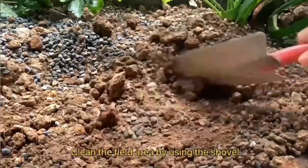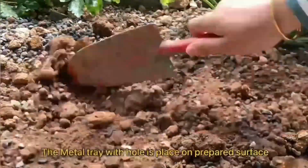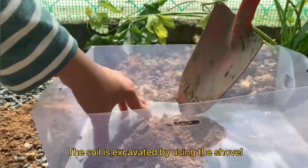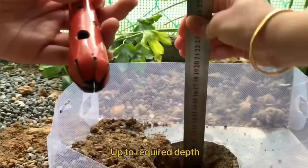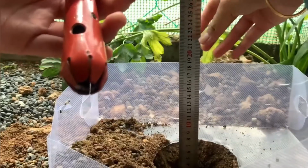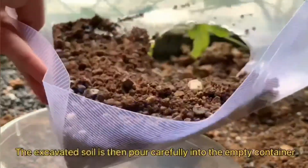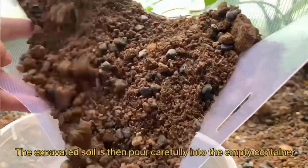Clean the fill area by using the shovel. The metal tray with the center hole is placed on the prepared surface. The soil is excavated by using the shovel to the required depth. The excavated soil is then poured carefully into the empty container.